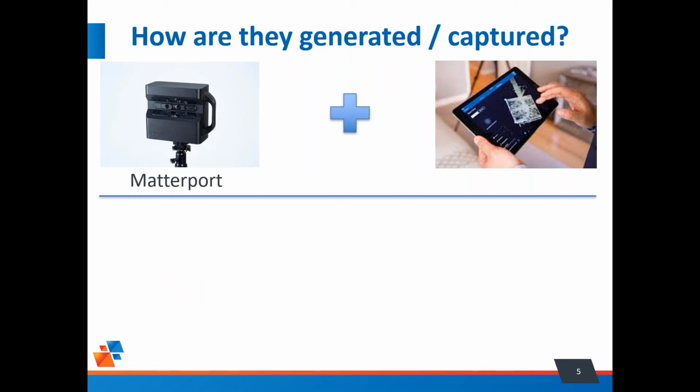It is a focused light scanner, which means it projects a UV light grid on faces to get the geometry, so to get the location. Still XYZ, still can be changed to a point cloud, but it uses UV light. So it's a little challenging with exterior conditions, but it is extremely fast.